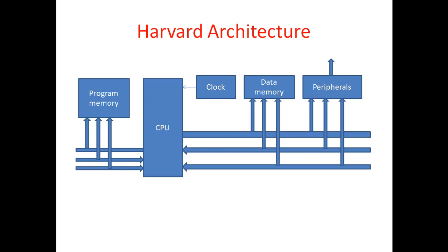Harvard architecture. Harvard architecture physically separates memories for instruction and data, requiring a dedicated bus for each of them. Instructions and operands can therefore be fetched simultaneously. Most DSP processors use a modified Harvard architecture with 2 or 3 memory buses, allowing access to the filter coefficient and input signals in the same cycle.